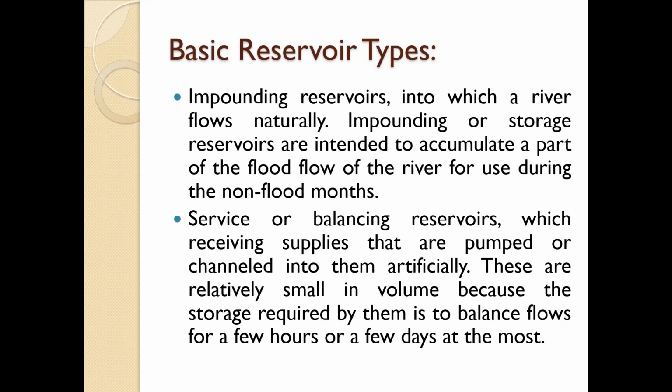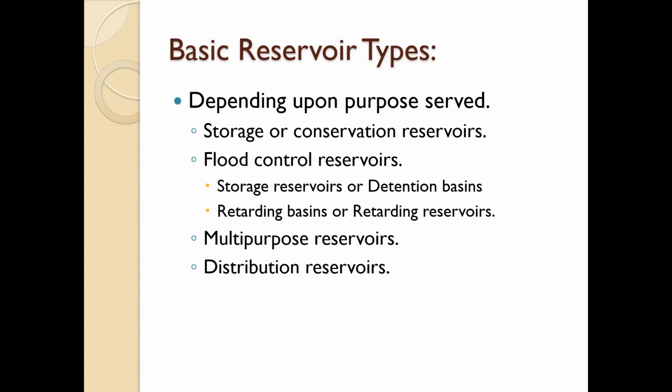Then the service or balancing reservoirs, which receive supplies that are pumped or channeled into them artificially, and these are relatively small in volume because the storage required by them is to balance the flow for a few hours or for a few days at most. And in the same way, depending upon the purpose served, the reservoirs may be divided into the storage or conservation reservoir, flood control reservoir, and multi-purpose reservoir.